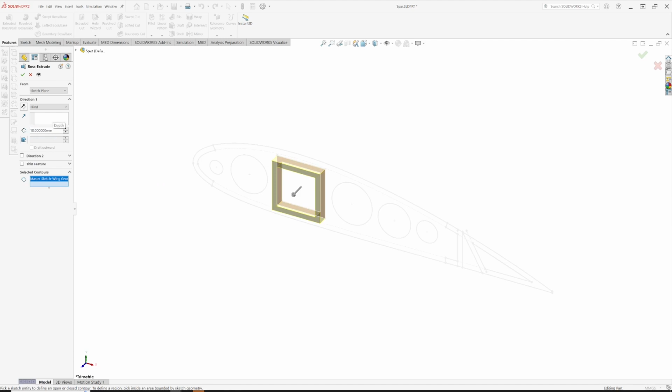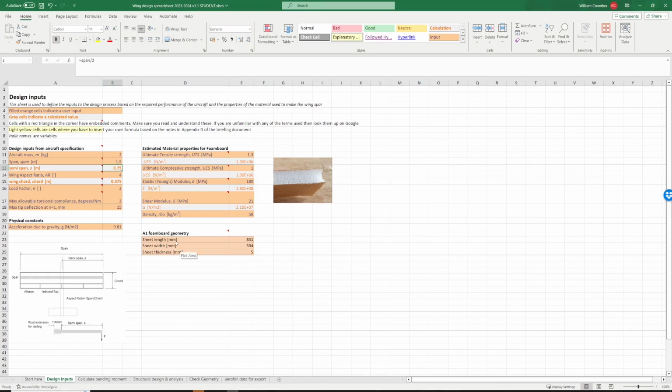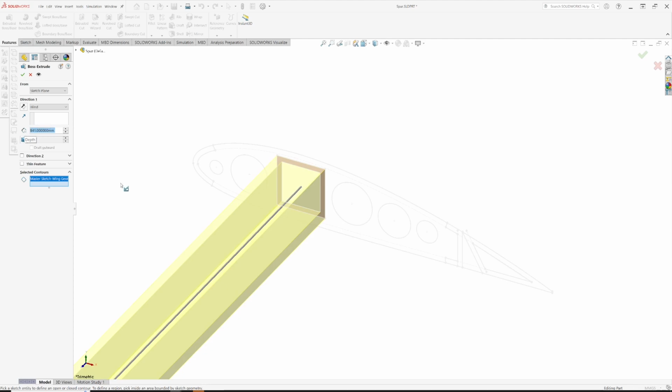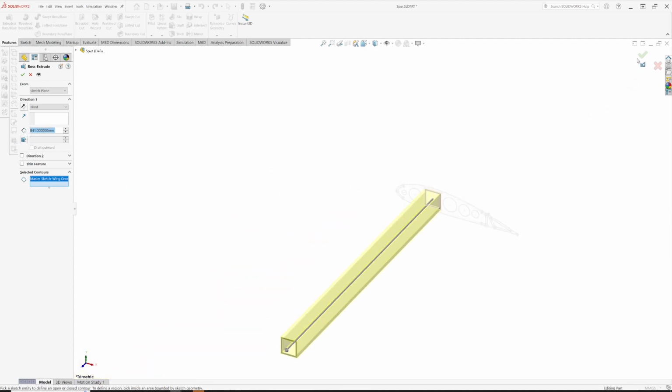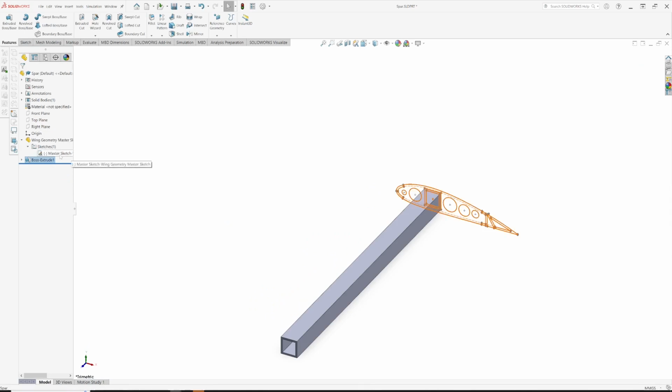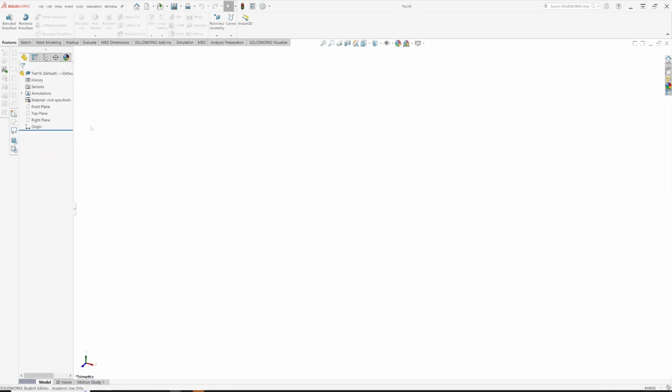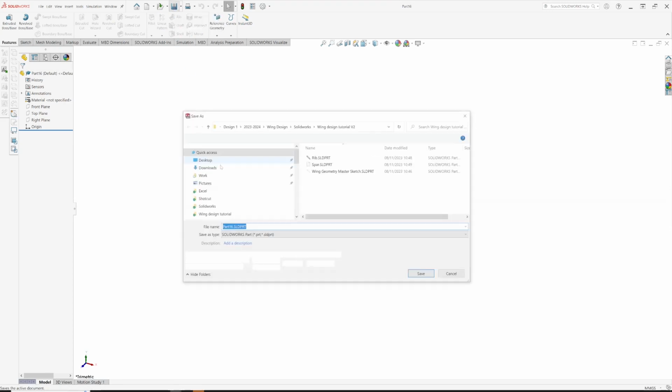This time, in terms of the length, what we want to do is use the full width of the foam board. The sheet length is 841, so let's make the spar the whole length of the foam board. Let's put 841 in there. There we go. Tick that, hide that sketch again, do another save, job's good. Keep going. Let's do the trailing edge spar next, or rear spar.